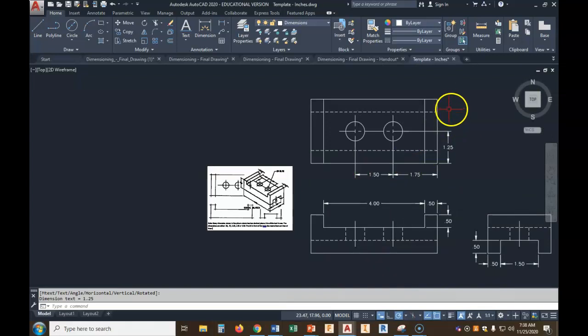You want that close to this. We'd never want to draw a leader through a corner, like where that hidden line hits that. We would never draw it through the outside corner. We cannot cross a dimension line, so a line with a number in it.